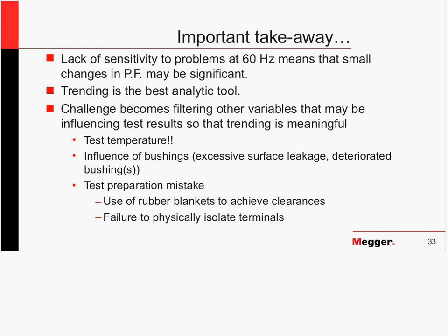So what kind of implication does that have? It tells me that my power factor has a lack of sensitivity to moisture at 60 hertz. That means that if I'm going to rely on power factor to assess how healthy my insulation systems are, then I better take any change in power factor seriously. But the danger there is that I don't want to overreact every time I see a small change in power factor, chasing down all these different possibilities, because a lot of the time it's going to turn out to be a false reaction and a waste of time.